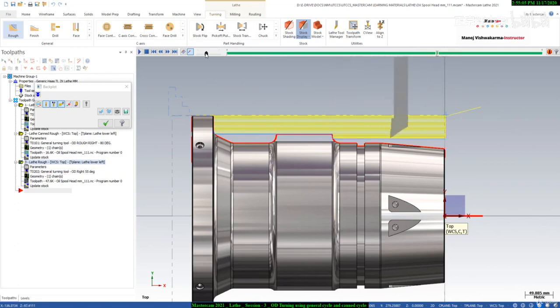So it will remove the possible area material. Right. So as you can see, if we use this tool for this area, then our tool will collide with this material, because clearance is not enough as per this curvature. So this tool path is also gouge free.